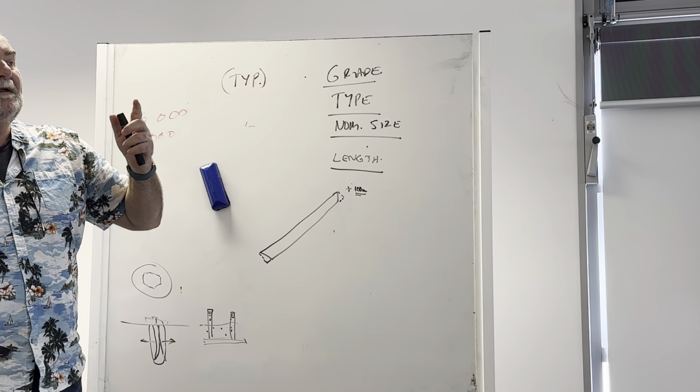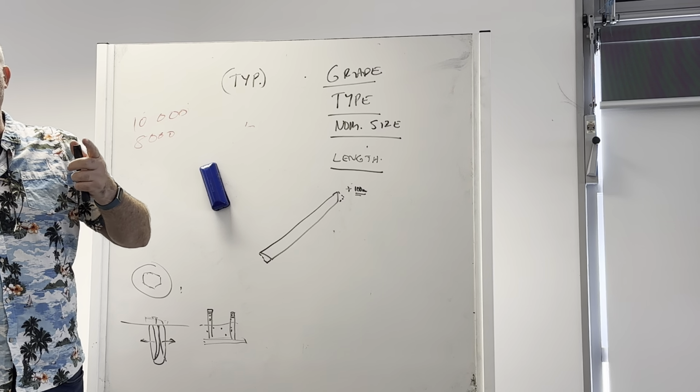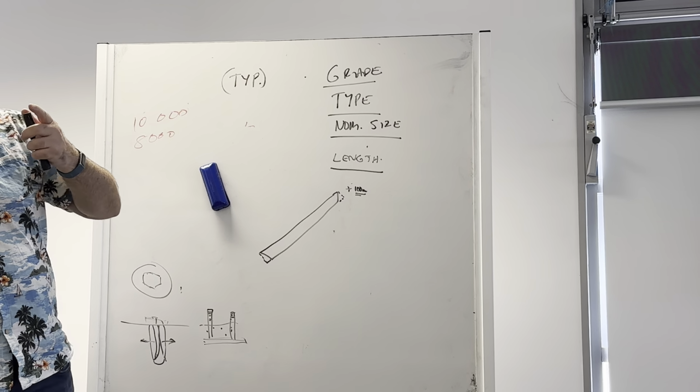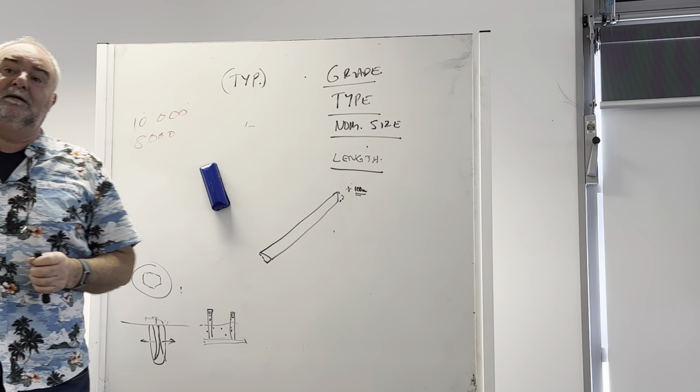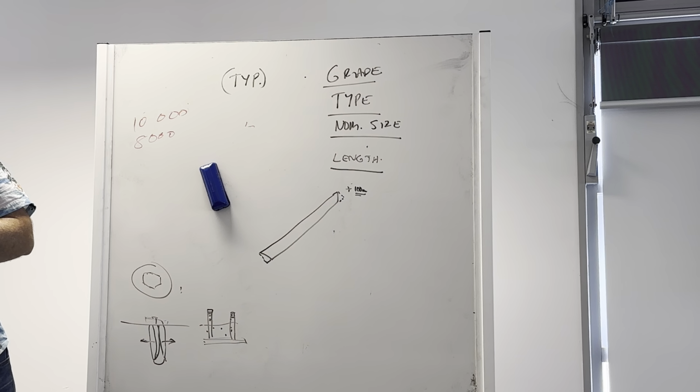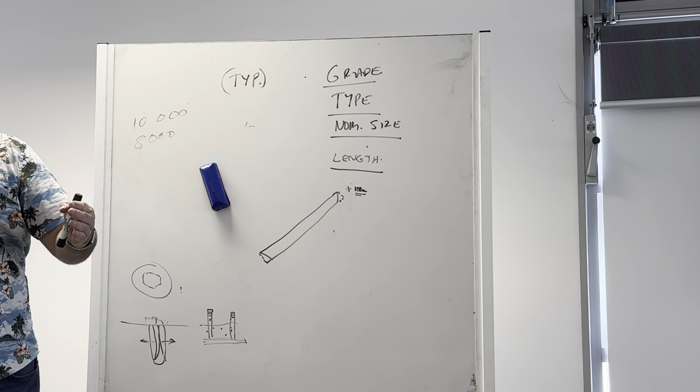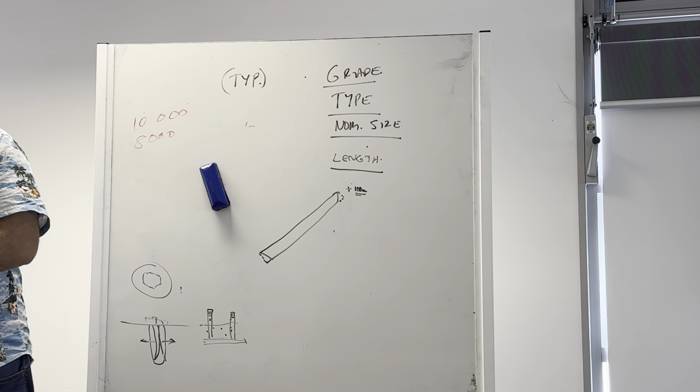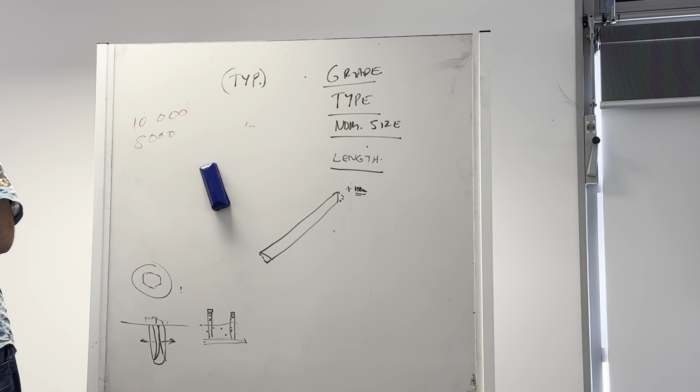As a general rule, believe it or not, they actually use a 10% factor for cutting, because you can't always get the timber the lengths you want. So say it came to 6.3 and you can only get 6 metre bits, then you're obviously going to have to buy another 6 metre bit and cut that off. Now some timber yards will say, oh, you can take a wee bit off that, mate, but others will say, no, you've got to buy the whole shebang.